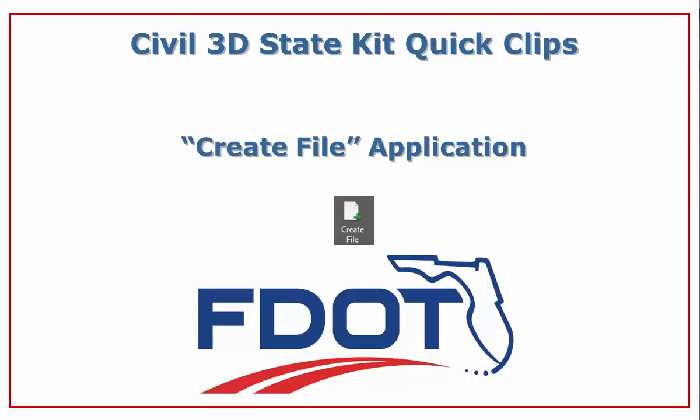The Create File application is used to create new design files using FDOT naming conventions. All FDOT project file delivery and QC processes are based off of following FDOT file naming standards. The Create File application automatically selects the correct drawing template, sets the active layer filter, and will also set the coordinate system for the file.